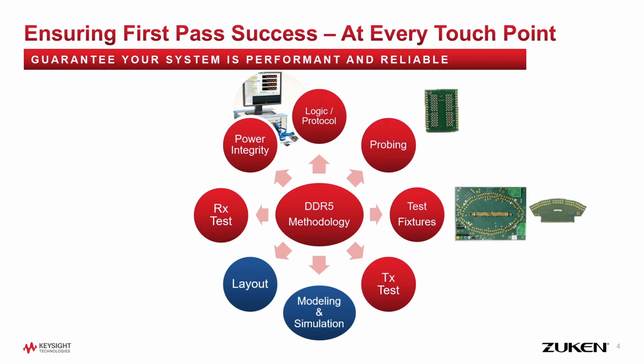And then once we know which particular lines are challenging or which particular lines have an issue, we could then go in and probe. Probing means that we need brand new risers and interposers designed for DDR5, redesigned so that they have very minimal crosstalk and they're not increasing the loading on the channel. Then we also need brand new test fixtures which enable test and measurement equipment to be able to access and break out the signals that we want to be able to receive.